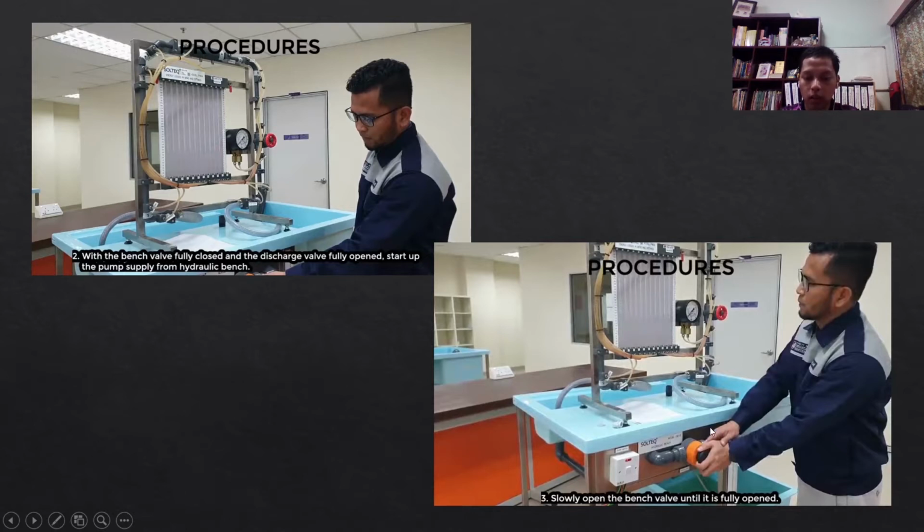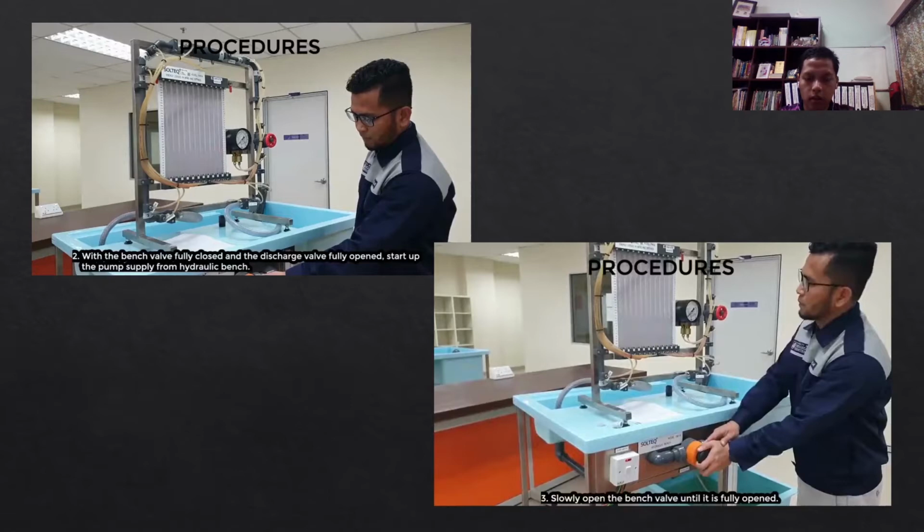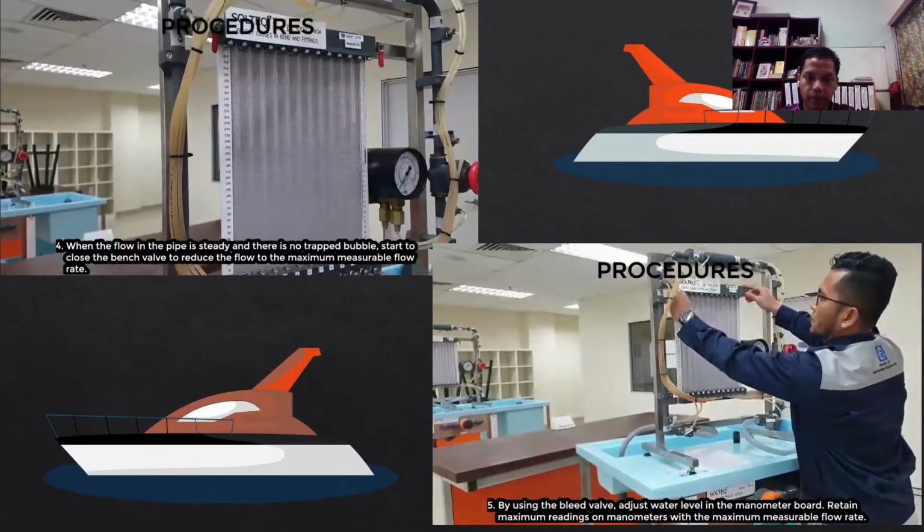Number 3 is to slowly open the bench valve until it is fully open. This is the bench valve, and it opens slowly because we don't want the water to go into the manometer bank fast, so we want it to be slow.